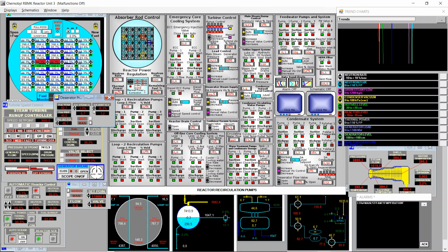Not sure that the aerator has some effect at this point, because I'm not sure we are venting. Yes, we're venting. I see here the value, and I'm decreasing it, so probably decreasing the aerator vent opening will slightly increase the generated load. I cannot go below 48 in the pressure power set point in the aerator. I will leave it at 5%.